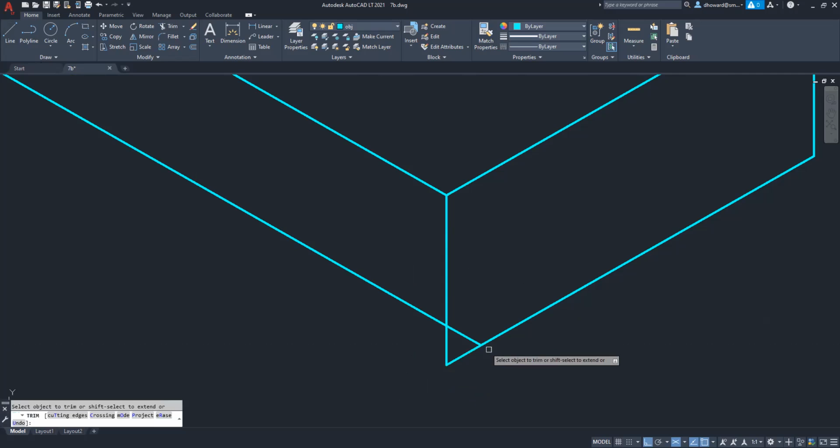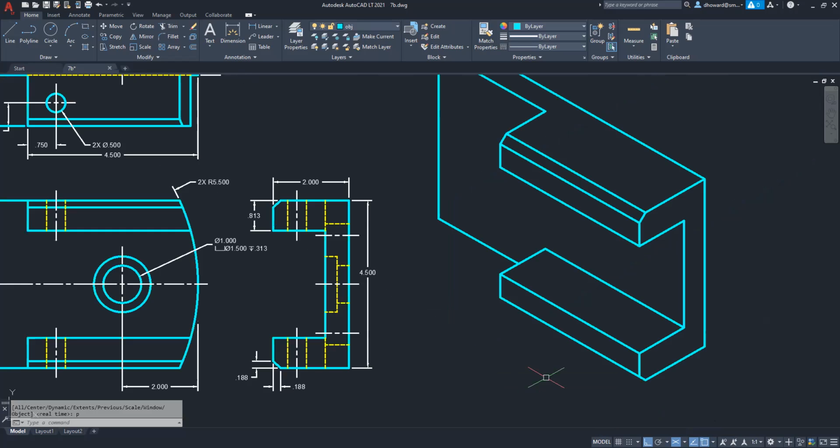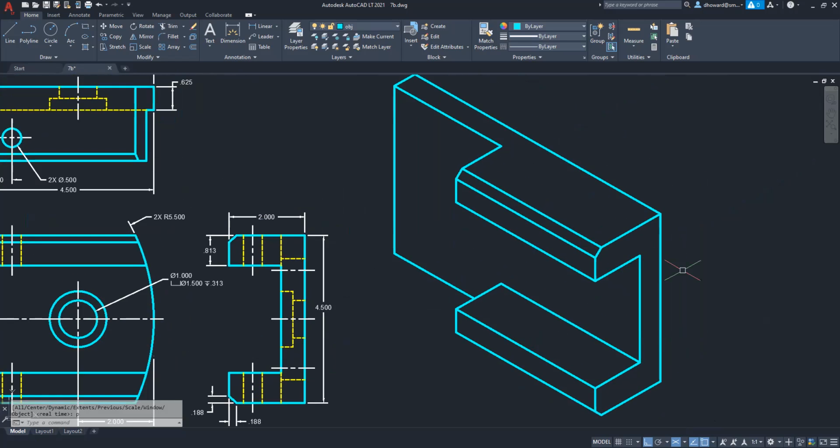And then we made the chamfer by going up 0.188 and connected it to this one. So these legs are the same length. They're both 0.188. And then it's this corner that's getting machined away, right? And it leaves this, and it looks like the same line at that particular angle. Anyway, I know it looks weird, but that is the deal.